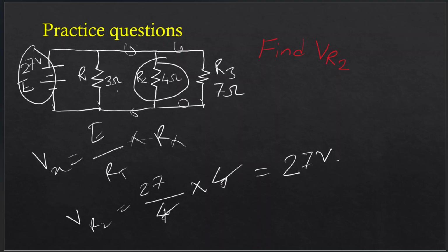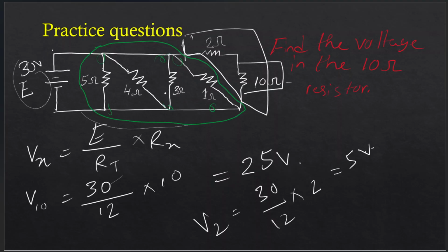Simple. So again, remember, for parallel connections, the voltage is the same. So the voltage divider is not needed for parallel connections. Again, that important point, RT here is the total resistance of the series connections. So even if we have parallel connections like we had here, for RT we will only use the total of the series part, so 10 plus 2, here 12, not the entire circuit.